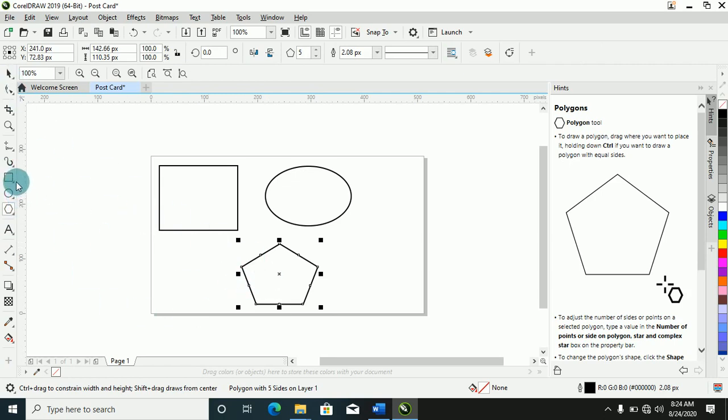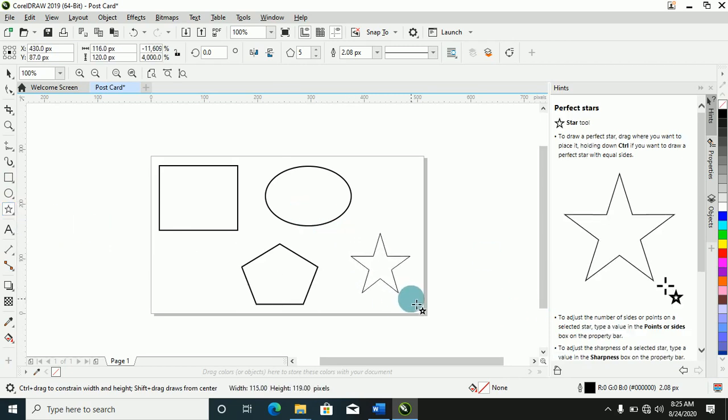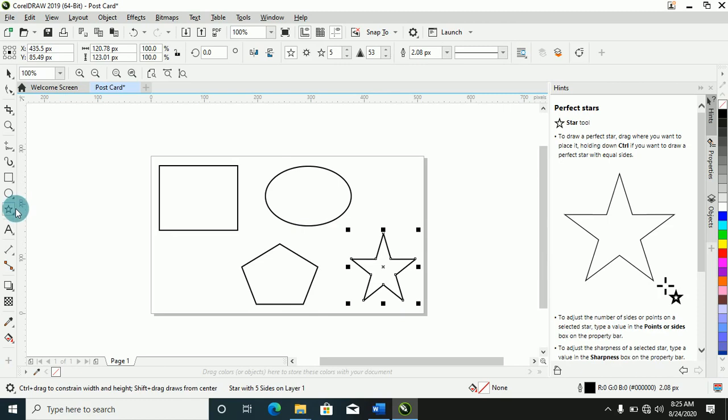We have more. When you check at the rectangle, there is a black arrow at the end. You can see that I had a rectangle and a 3-point rectangle. So these are the additional ones that you can do. When you check the ellipse tool or the circle tool, you have the same thing. When it comes to polygon, polygon has different types. If you want to draw a star, you can get it over here. Then you draw it. If you don't need a star, you need a different design, you can go in there.